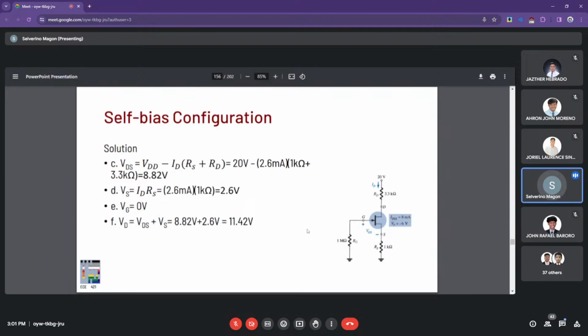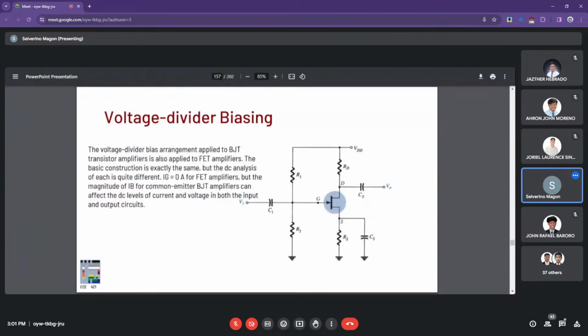So what this means is that at Q point, you have a constant DC measured across the drain pin to the output. Anyway, this DC cannot be seen from the output pins, because again, I think we mentioned the capacitors last time. So the capacitors essentially provide isolation for the DC.